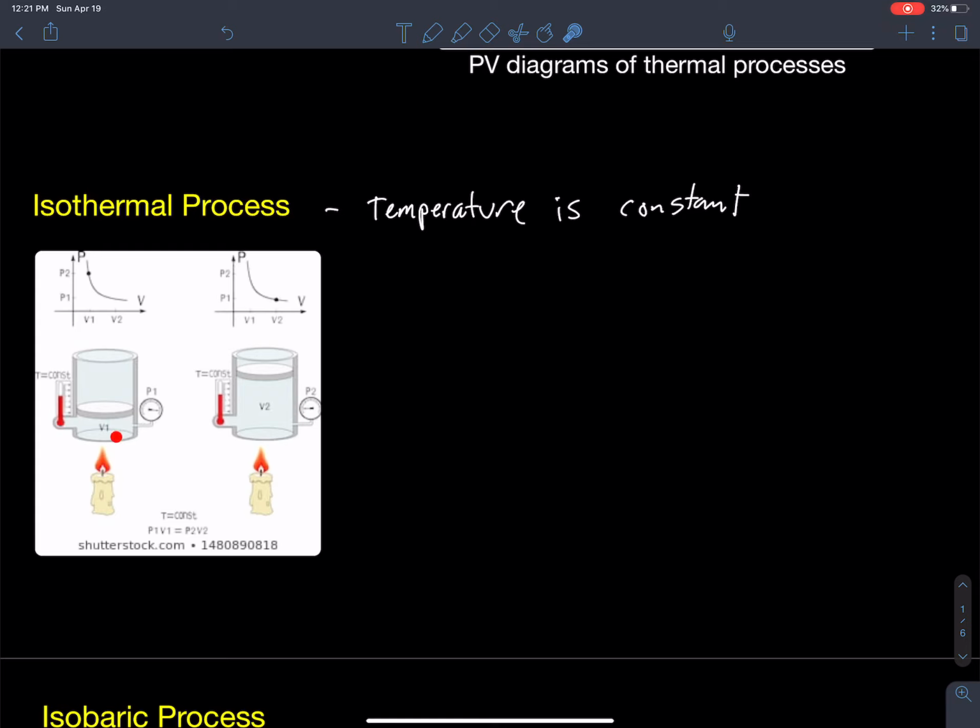In order for my temperature to stay constant, that gas immediately has to transfer its energy to the piston. That head has to have very little friction, okay? So that heat energy going in immediately causes a volume change without changing the temperature, and then that system will follow an isothermal process that looks like that. That's for that specific temperature.